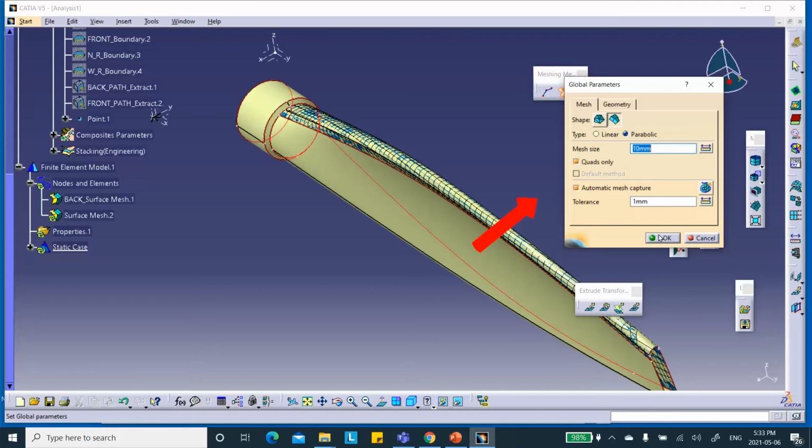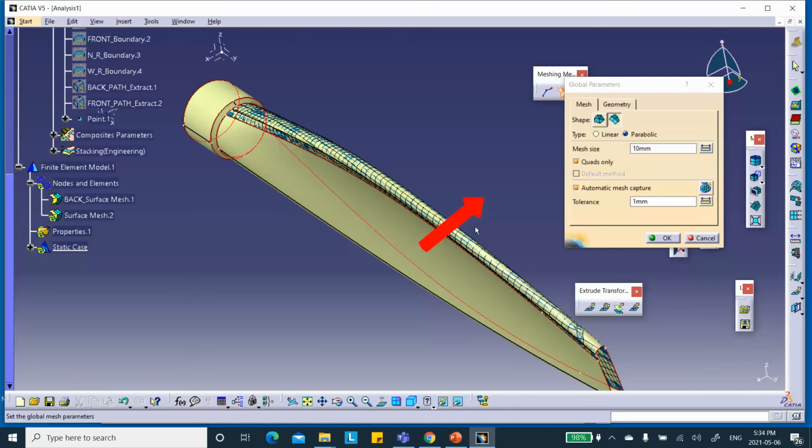The only problem is that we're going to check the direction of the shell elements, because that's one step that I forgot to do, and unfortunately I have to make sure that the direction of the normal to the shell element is opposite to the direction of the join, or let's put it this way, the direction of the shell element is in the draping direction, which is inward.